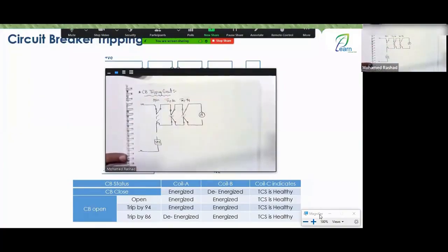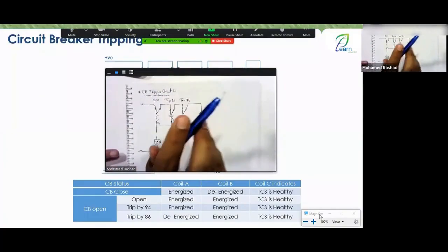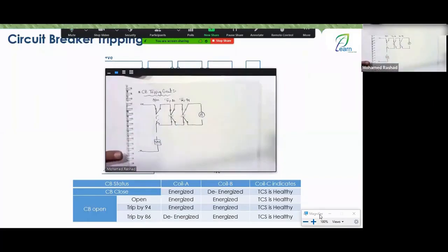Focus with me. Now the idea is quite simple. The coil, what's its current state? Now it will receive a positive from here, like this, like this, like this, until it reaches it. Until the positive reaches it, okay? So the positive has passed through all this wiring. Therefore, any cut in this path means the coil won't receive the positive, right or wrong? You told me right. Okay, this means that it monitors the entire path, right?